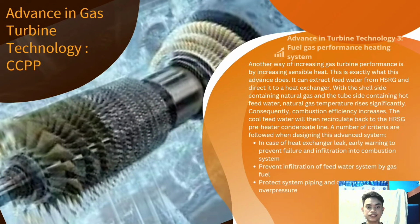Another way of increasing gas turbine performance is by increasing sensible heat. This is exactly what this advance does. It can extract feed water from the HRSG and direct it to the heat exchanger. With the shell side containing natural gas and the tube side containing hot feed water, natural gas temperature rises significantly. Consequently, combustion efficiency increases. The cool feed water will then recirculate back to the HRSG preheater condensate line.